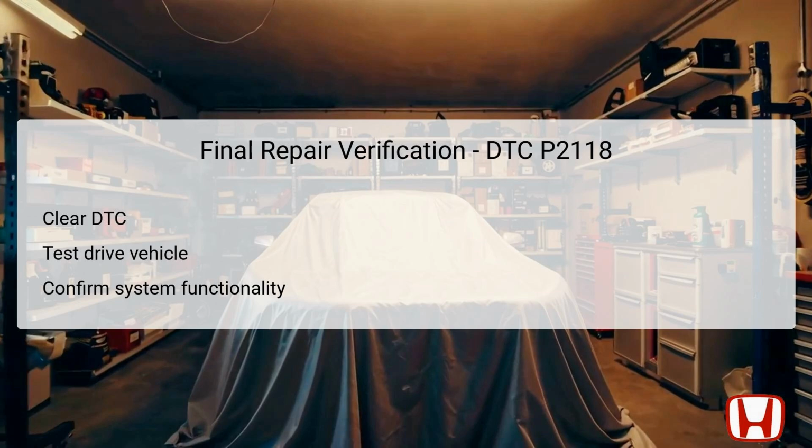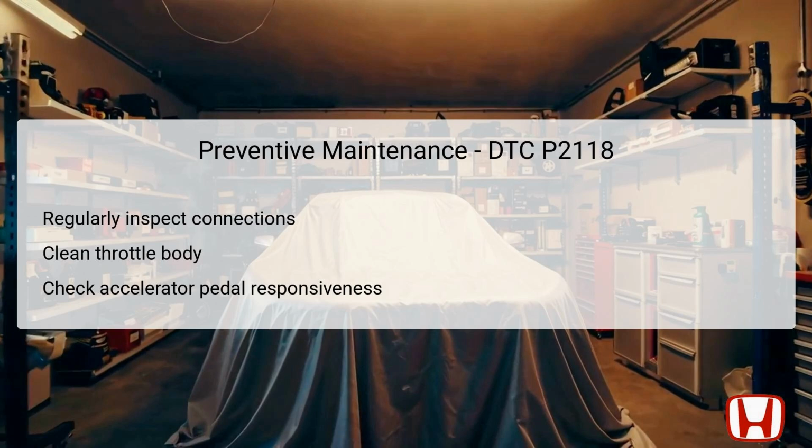Successfully re-establishing the intended performance level and confirming no returning error codes is a culmination of effective diagnostics and successful repairs. Preventive maintenance is pivotal in ensuring the longevity and performance of the throttle actuator system in the Honda Odyssey. Regular inspection of electrical connections, especially around the throttle body and PCM, should be conducted to identify any signs of wear, corrosion, or loose terminals before they lead to performance issues.